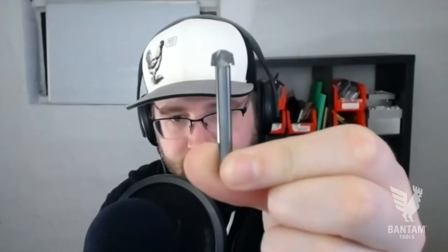And that's an end mill there. I mean, to give people a better idea, not to cut you off though, Pete. For the flat end mills, especially for our machines, we typically like to use the flat end mills for adaptive clearings, contours, that type of stuff. Just because, like you were given an example of when we use engraving tools and that type of stuff.